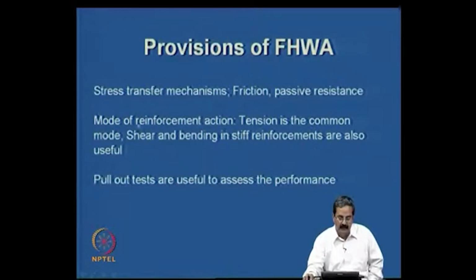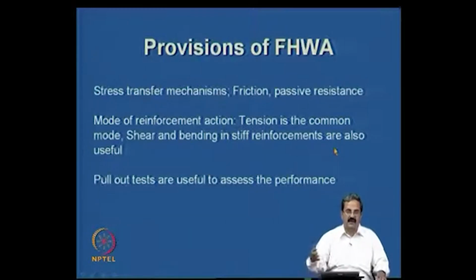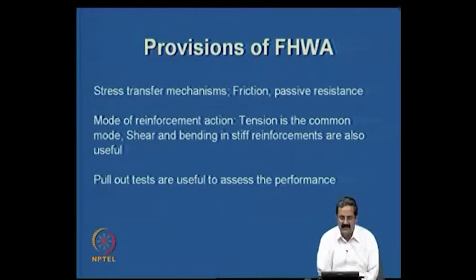So the mode of reinforcement in reinforced soil is essentially tension. That's the main thing. But then you can also take advantage of shear and bending in stiff reinforcements. Okay, that's also useful. Sometimes, for example, even confinement action, geocells is one material. So one can do a lot of composite reinforcements. But what it means is that essentially we can understand some of these things in a better way and then